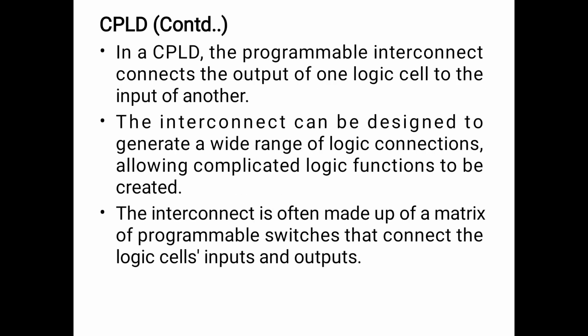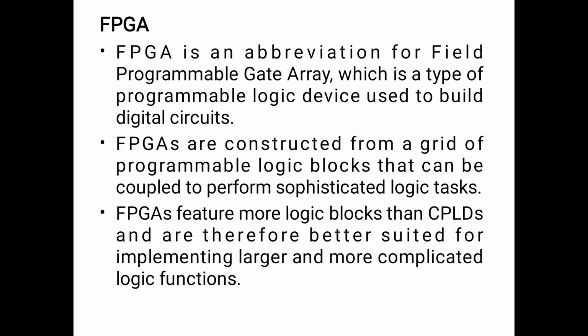In the CPLD, the programmable interconnect connects the output of one logic cell to the input of another. The interconnect can be designed to generate a wide range of logic connections, allowing complicated logic functions to be created. The interconnect is often made up of a matrix of programmable switches that connect the logic cells' inputs and outputs.